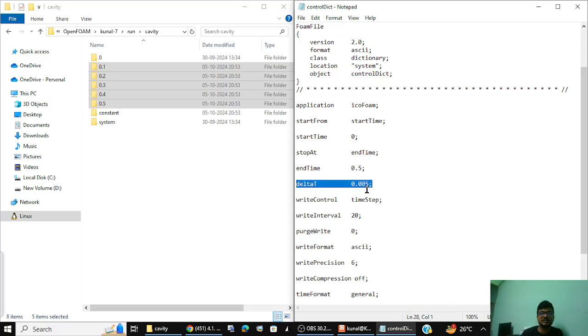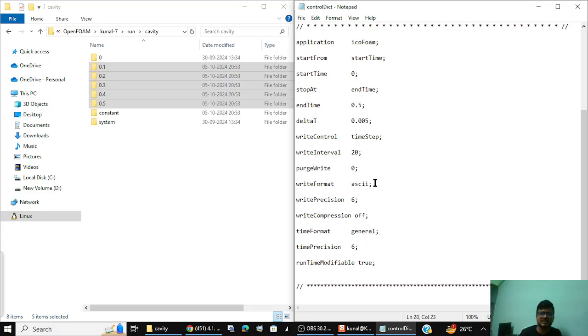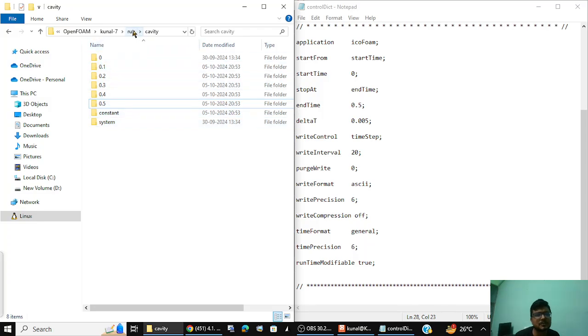But sometimes the simulation becomes stable in the near future, and then you decide that it is comfortable to increase the time step so that I converge faster. So accordingly you can do it at runtime. The simulation is running and you are modifying the time step, so that provision is also there, again for the advanced user. But just to summarize the key entries that we are studying right now.